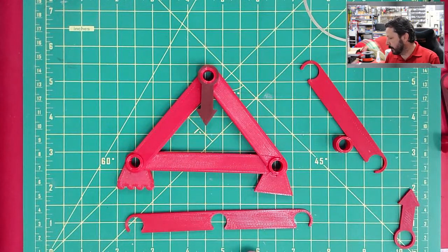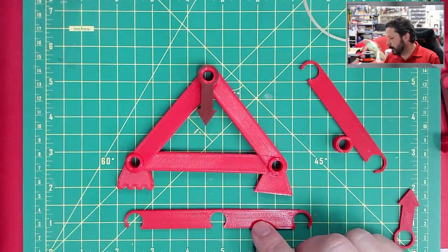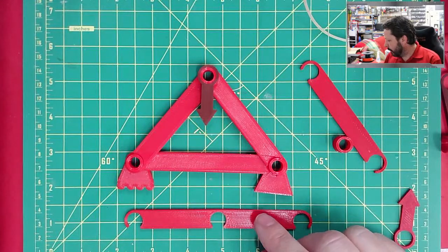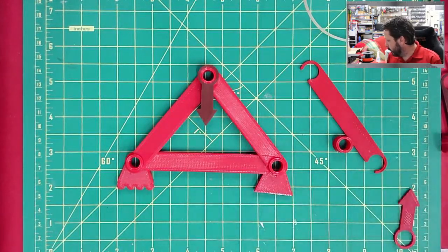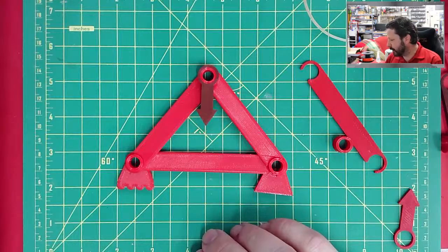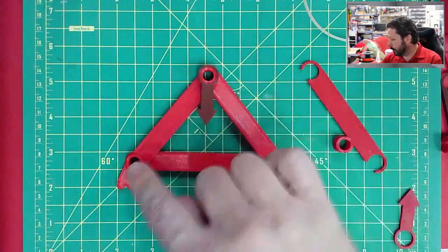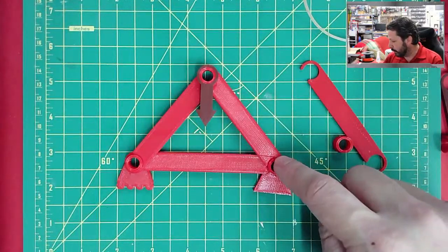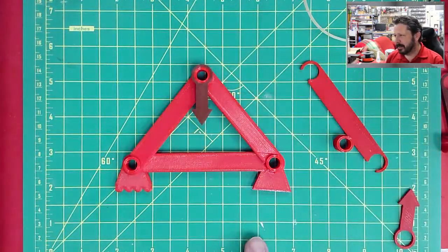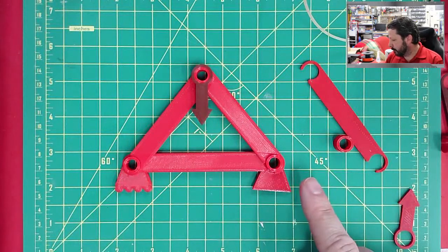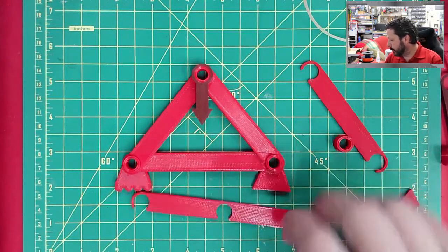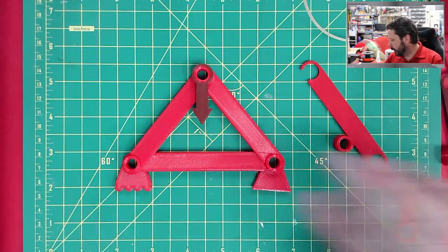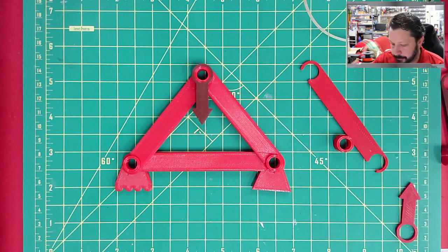This piece couldn't go in a truss. This piece would have to go in some sort of frame or machine or something like that. So when I'm analyzing something like a truss, every member is only connected to all the other pieces in the truss by 2 pins, one at one end, one at the other end. And there's not any pieces like this one where this member has 3 connection points. So each member only has these 2 connection points.